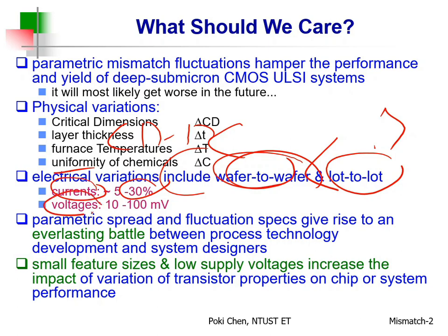And how about voltage? Hundreds of millivolts. That is what you need to face. So if you don't pay attention to such kind of parametric mismatch, then the yield or even the performance will be quite awful. It will be very scary. So you must find a way to solve them.